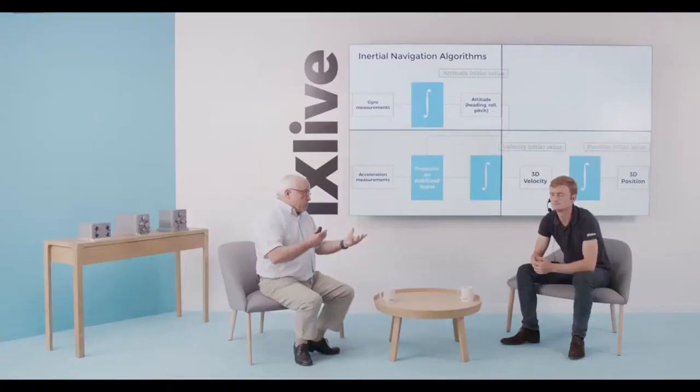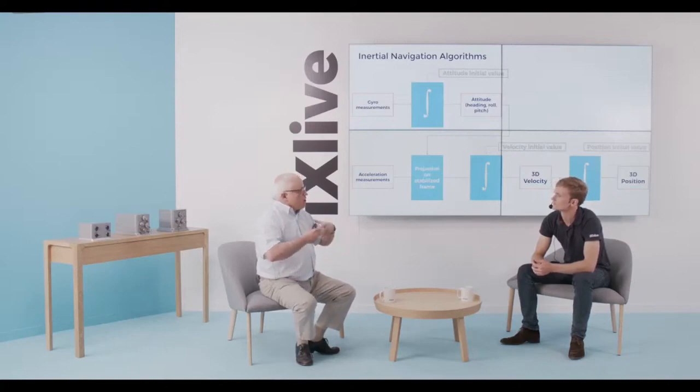Yes, the GNSS is working in a differential mode between the two antennas, but with some accuracy. In order to minimize the impact of this accuracy on the heading provided by the GNSS, we need some baseline between these two antennas. And the third method is one which would use another sensor, a magnetometer, which will be able to measure the magnetic field.